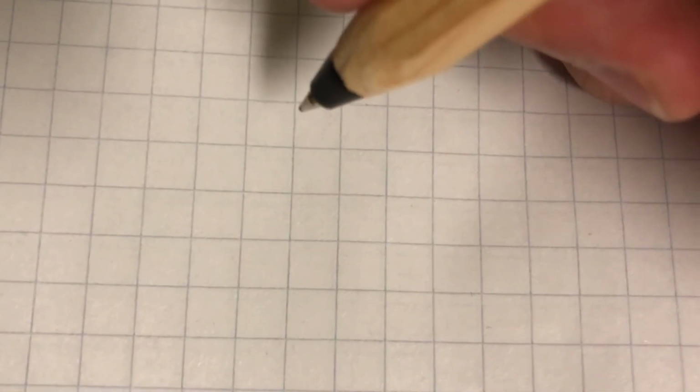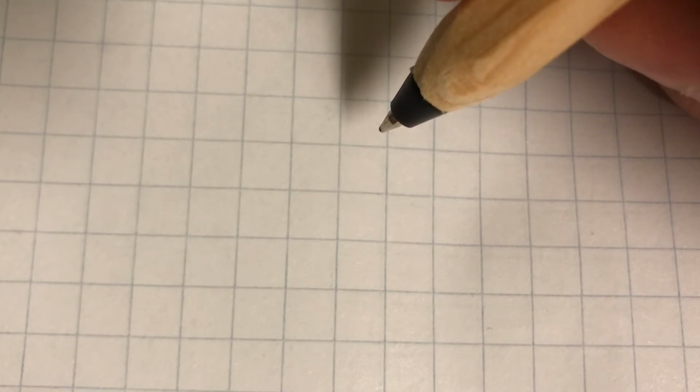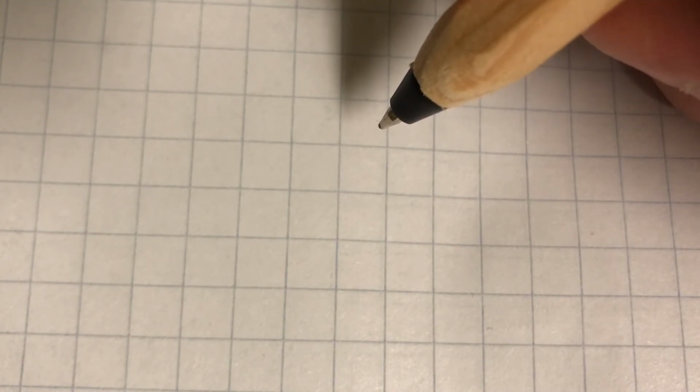Okay, so tone works in a very similar way as volume, in that it also uses a potentiometer, except it's used in combination with a capacitor. And the reason for this is because the capacitor is going to be serving as a filter for frequencies, okay? So when we're turning our tone knobs and we hear that very tight sound compared to that more gloomy sound from the guitar, that's a change in frequency, okay? And that's what the tone is doing here.